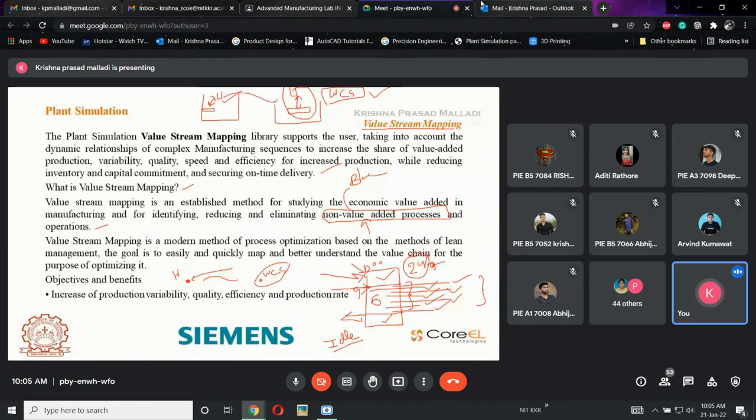And again there is a difference between home and WCS, that is called G54 in the programming language, work coordinate system. Whenever I need to stop the machine, it comes to this position, and it will end. So for the next run, when I switch on the machine I need to recenter again. I need to go to this location manually, give the G54 command and set the programming, that is called G54. Definitely setting this G54 for the WCS will take some time, at least maybe 5, 10 or 15 minutes based upon the machine complexity.